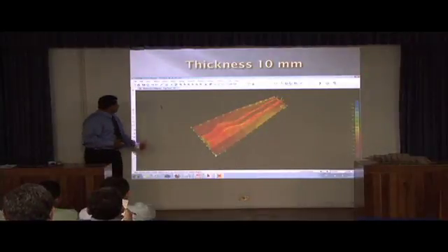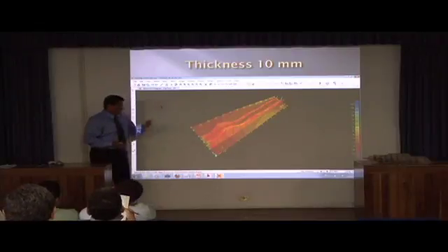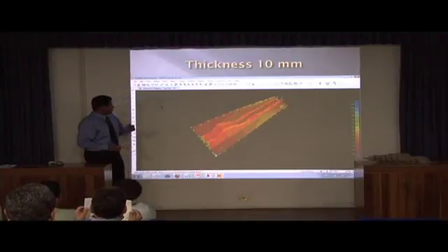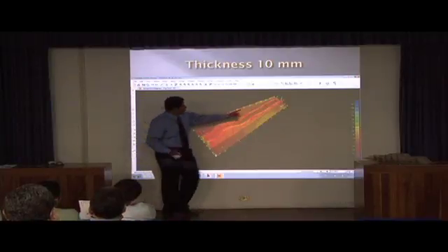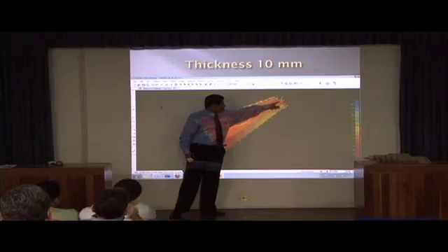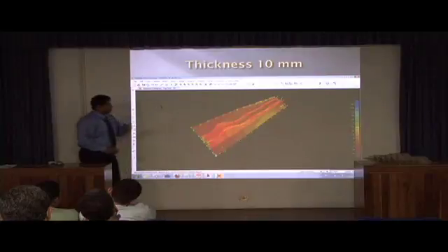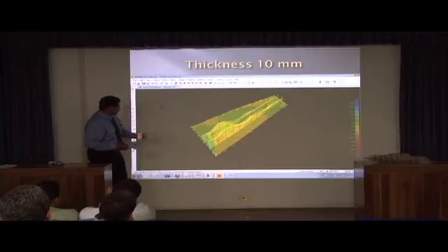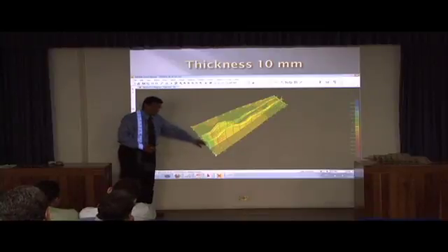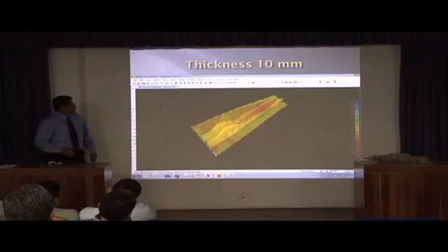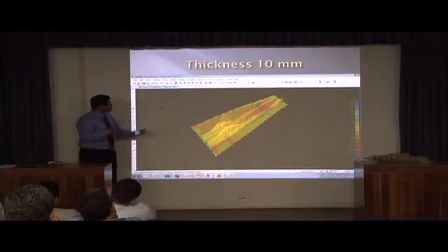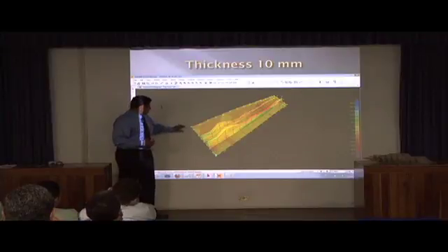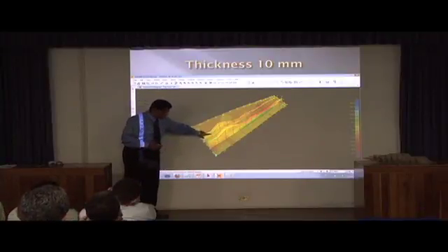Now the stresses. We have here the longitudinal stresses. The highest value is 257 kilograms per square centimeter, located in the joint here, in the highest joint of the bracket of engine foundation 2. Now we have the shear stress, and the highest value is located in the flange of the engine foundation, which is a built-in. Now this is the stress in transverse direction, and the highest value is 185 kilograms per square centimeter, located in the flange of engine foundation 2.